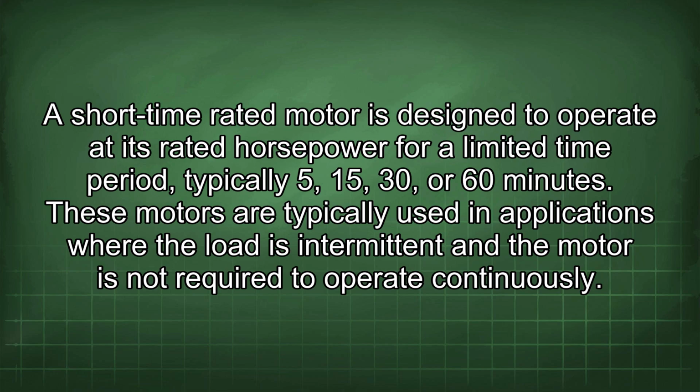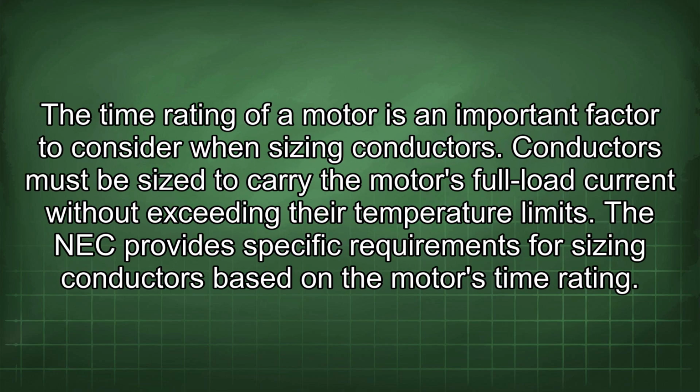These motors are typically used in applications where the load is intermittent and the motor is not required to operate continuously. The time rating of a motor is an important factor to consider when sizing conductors. Conductors must be sized to carry the motor's full load current without exceeding their temperature limits. The NEC provides specific requirements for sizing conductors based on the motor's time rating.